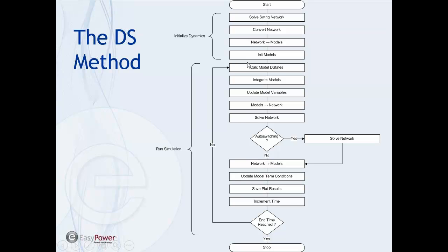It also means that the power flow solution after entering stability is different than what you would have in a regular power flow simulation. If you scale a motor in power flow, it scales both watts and VARs down. That does not happen in dynamic stability because the scale factor is applied to the mechanical load on the shaft, so your VARs are not necessarily going to drop.